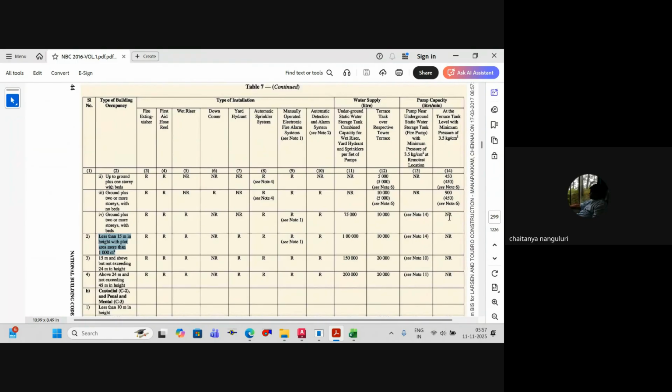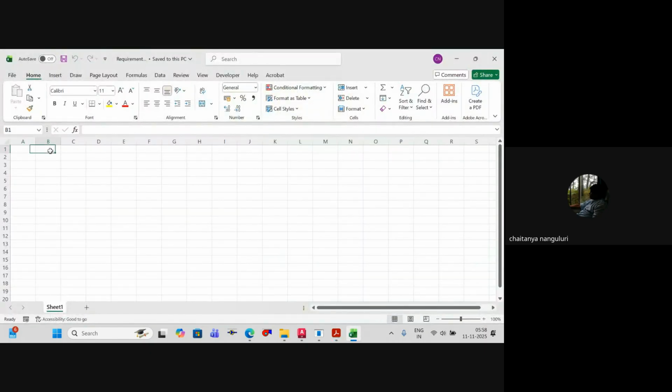Okay. But again, if the pressure is unable to meet 3.5 meters as per height, we might have to install one. Because at the end of the day, we should get that minimum pressure. Am I clear? Okay. Even though they have not provided it, we generally provide a booster pump if required. Clear? Yes. So now we are going to understand how to arrive at this particular one. So basically we'll just write it. I guess that will be better.